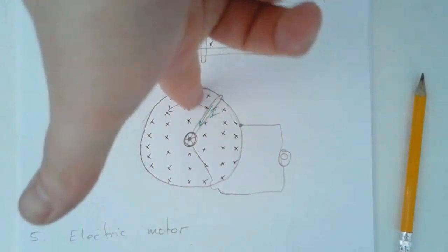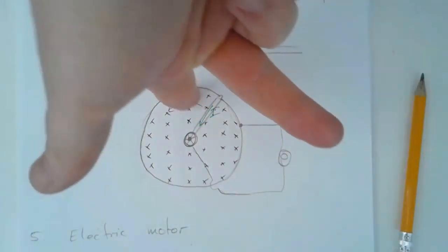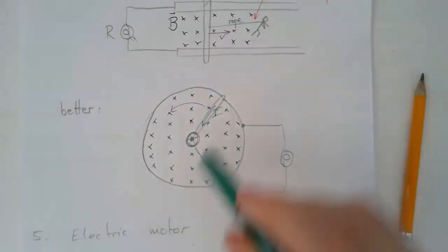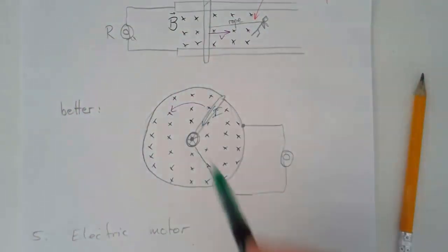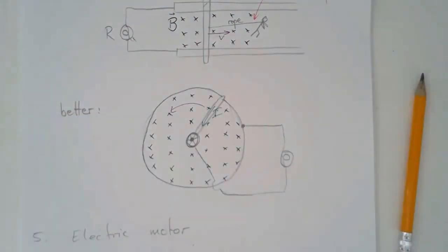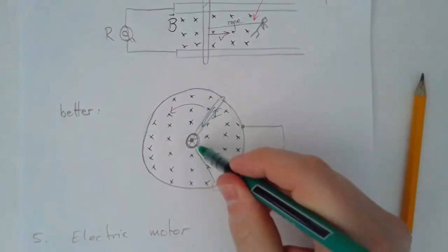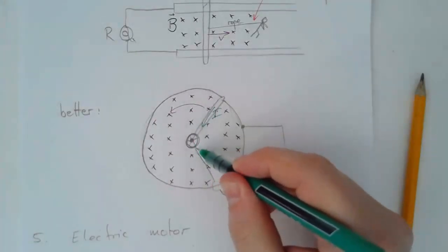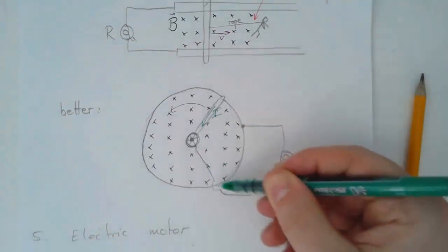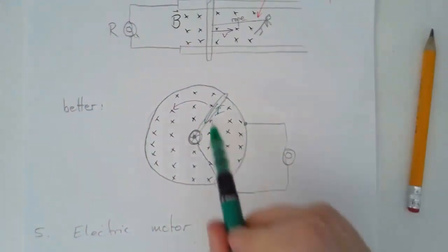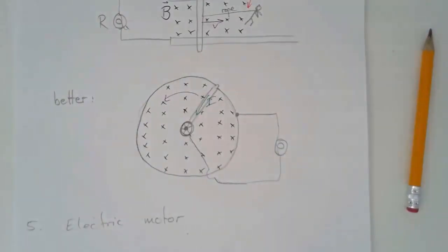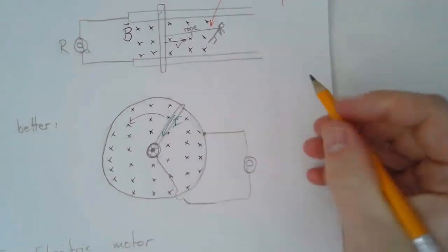Can I show this to you? There we go. Force, my middle finger here, this way. But I'm going to oppose that force because the wind's blowing against this, and with beautifully shaped blades, it makes it spin, keeps it spinning. And so I'm going to get a continuous current. Now you can imagine this gets hooked up via some kind of cable that goes underneath this whole setup, and it goes around here. And I get a continuous power output as long as something keeps it spinning. So we've just built our first wind power station.